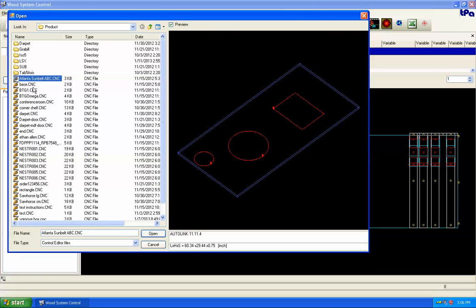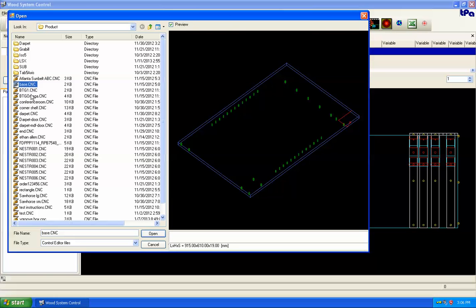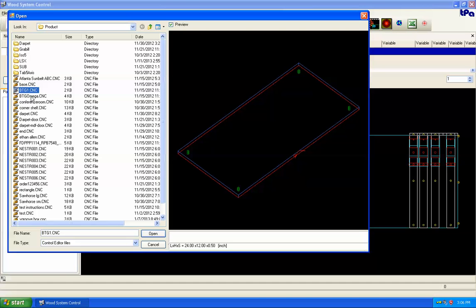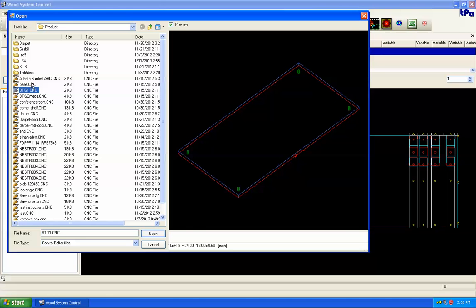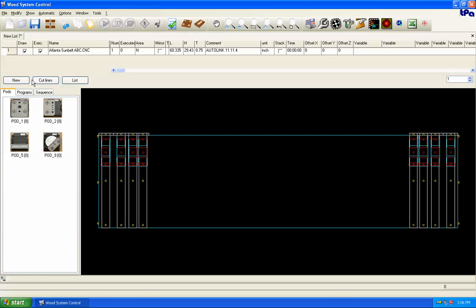As we look at the parts, you've got a three-dimensional view of the part, with the red being the routing and the green being the drilling, and the blue represents the edges of the part. So let's take this program here, and when we put the part in the list, we want to draw the part and superimpose it over the machine table. And we can draw all the operations, or if we have some operations that don't go through the part, then we're not really concerned about those.